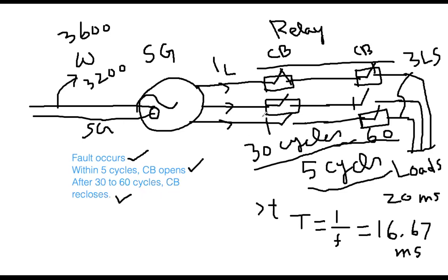But after reclosing, these circuit breakers are very intelligent, very smart. They are pre-programmed and equipped with intelligent controllers. It is automated. You don't need to do these things manually. It will automatically happen. And then, for example, it's a permanent fault, like a 3LS, 3-phase short circuit, or 3LG, ground. Like a tree has fallen and caused a short, and unless the operator from MLGW comes and removes it, it is going on, which is called a permanent fault.